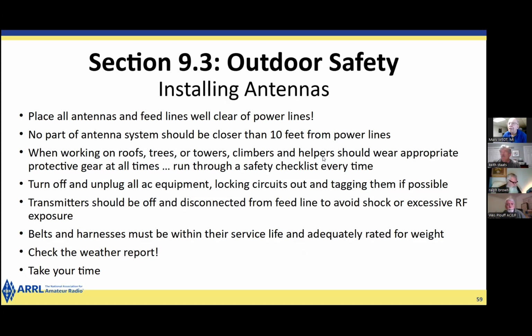Well, if you have a power line in the back of your lot, between your lot and the one behind you, and you have a 20, 30-foot tower or a mast on your house, if that mast fell over, it would determine how far away from the lot line and the power line you'd have to be. When you're saying 10 feet away, it's not from where it's standing straight up and down, but how far would that extend out into the property if that tower or mast fell down?